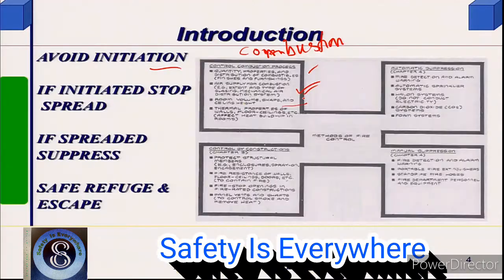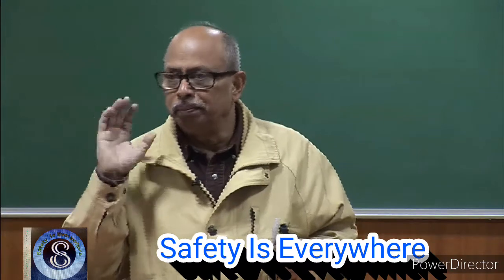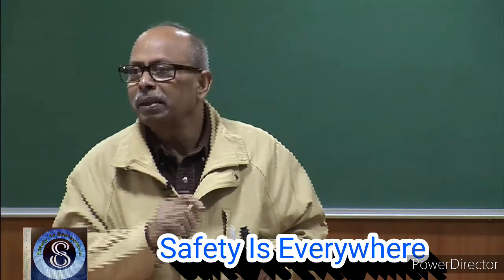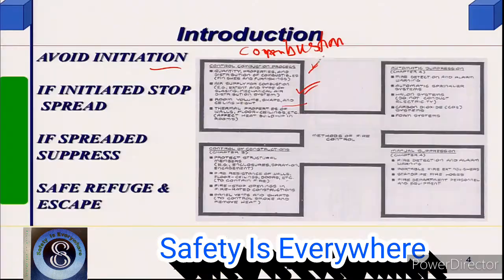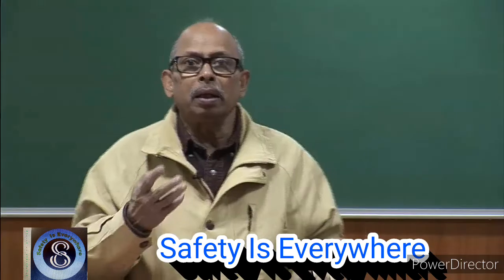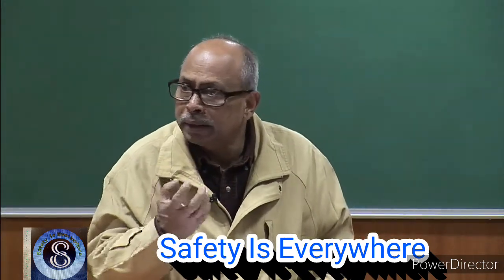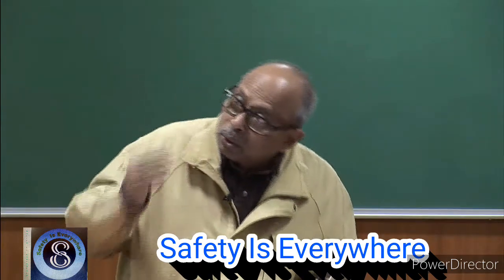We shall see that. Then since heat has to dissipate through the envelope or periphery of the room, their properties are important, particularly thermal properties. So that is related to initiation. If you want to control them, you will have to look into this. Then you can also do control by construction. That is what I was saying, structural fire design, protecting structural elements. For example, if it has initiated on its own, accidentally, it should not spread to the next room.